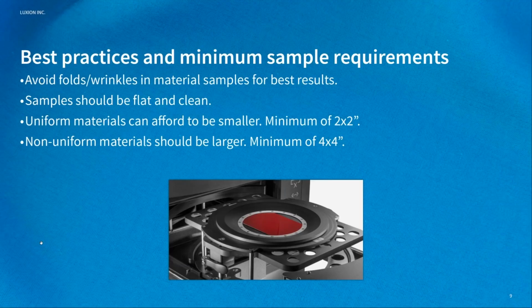Okay, we have a question from Stefano. How to set up lights in KeyShot to have the best accuracy on color reproduction. So what I would suggest for that is to use Grayscale environments.